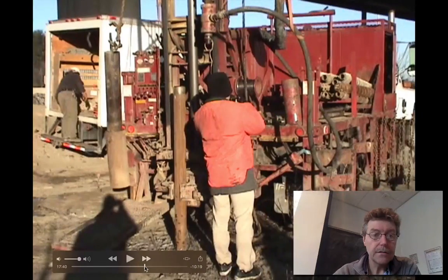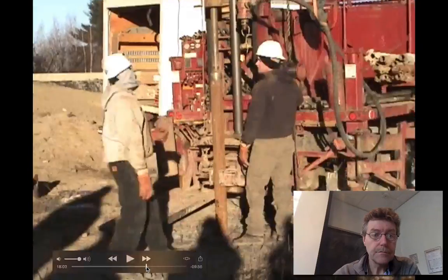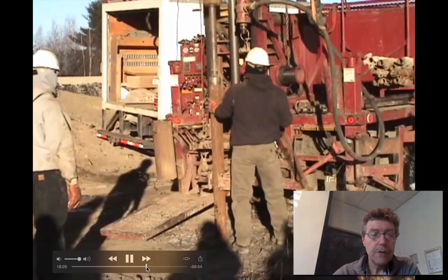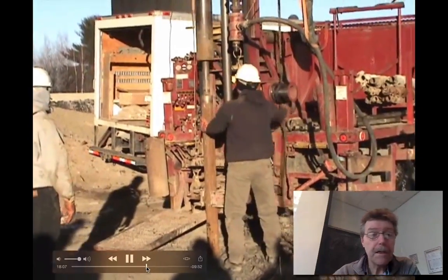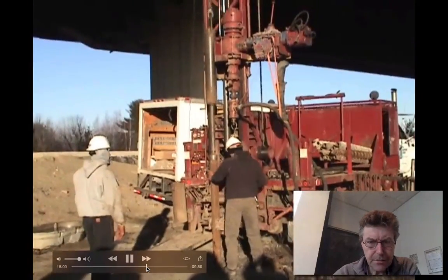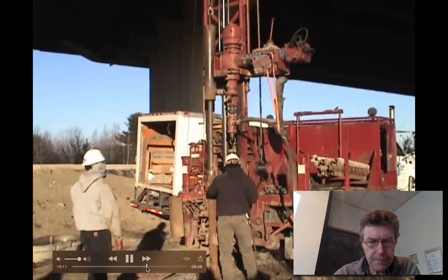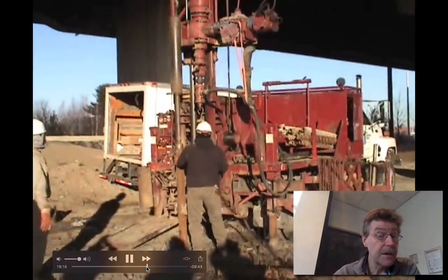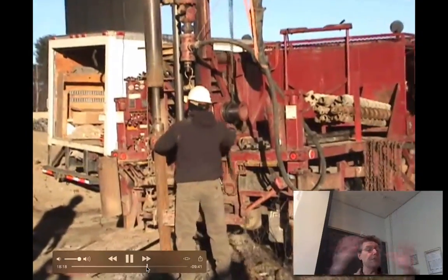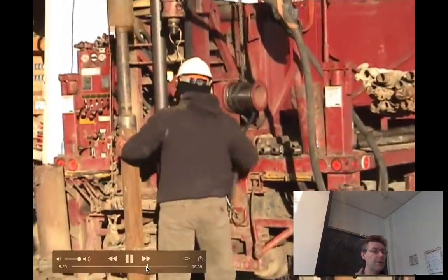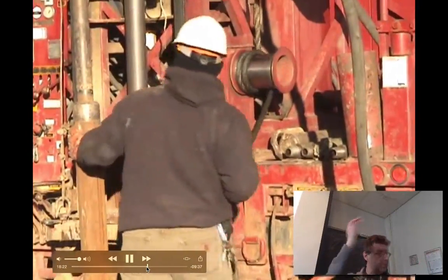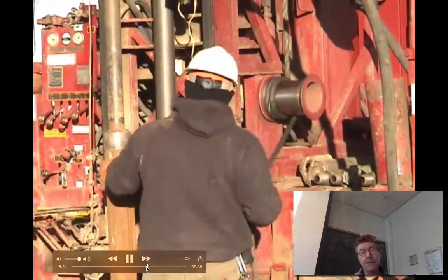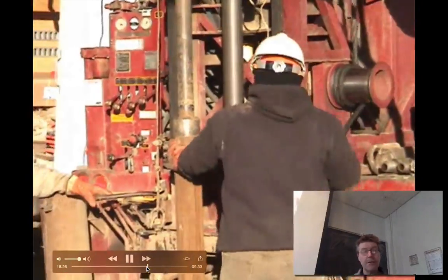So what else? We're going to talk about sampling. The other issue here is I'm not sure whether they're just advancing pipe or whether they're actually doing sampling. One of the methods of sampling is if you have this open hole, you go down to the bottom of the hole where you don't have a sample, but you've pulled all your pipe, and you want to be able to take a cookie cutter of exactly what it is.